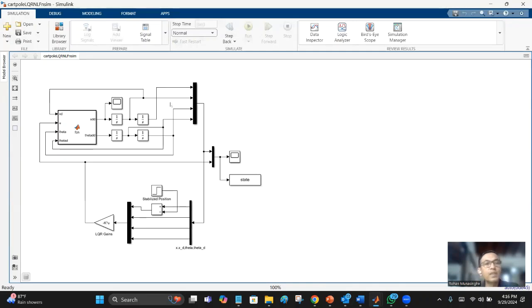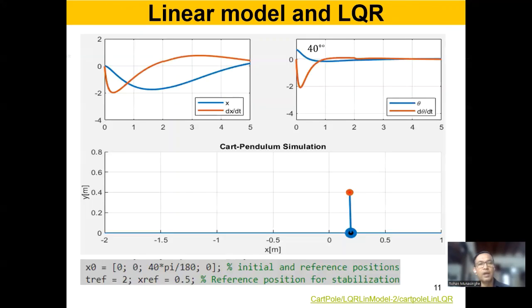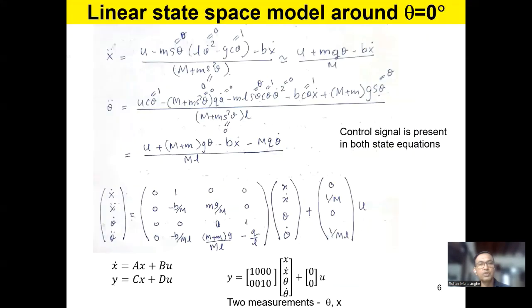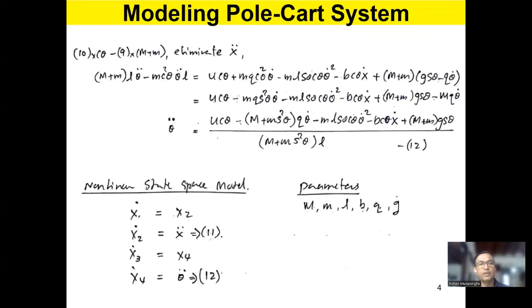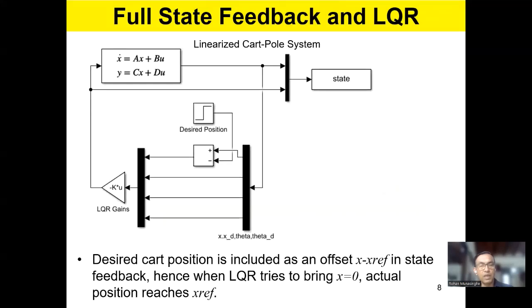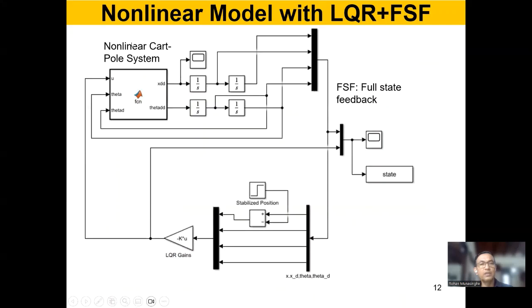Right, there you are. Can you see that? So there should be x dot, u, theta, and theta dot, because in our equations, we show these variables, right? If you go back to the PowerPoint, I can show you the two equations over here. Theta double dot depends on theta dot, theta, and x dot. So you need these variables to run your nonlinear model in Simulink. Okay, here. So I will update this slide.